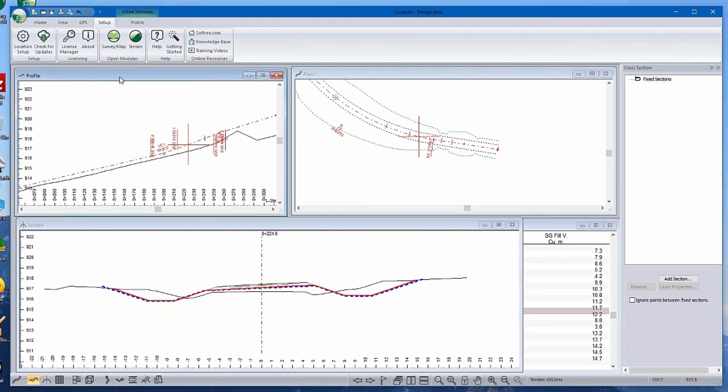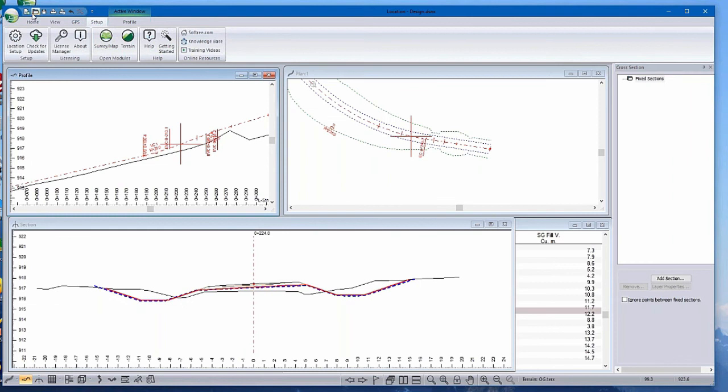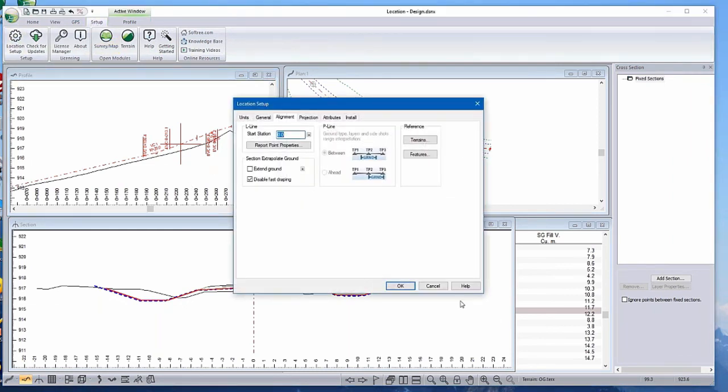Yeah, so there's an easier way to do this. I can create, somewhat automatically, a surface, an as-built design. So the way I do that is I go, there's something, disable fast draping. Oftentimes when you have surfaces that, I'll put it this way, RoadEng expects that the topo surface includes the other surfaces. So depending on which surfaces you have, they may actually be smaller. The topo surface may be smaller. Kind of a technical detail, but when in doubt, disable fast draping.